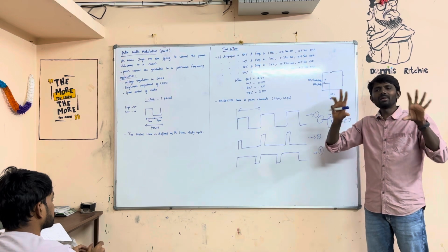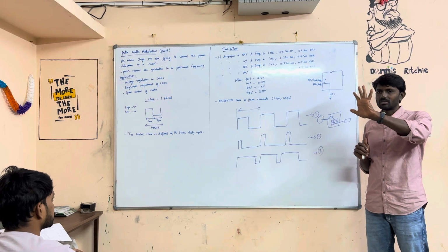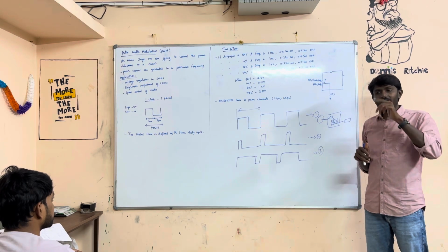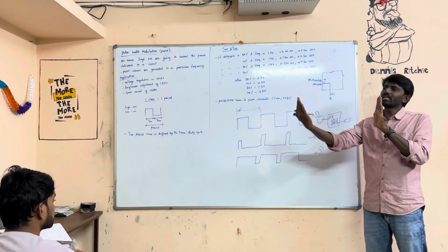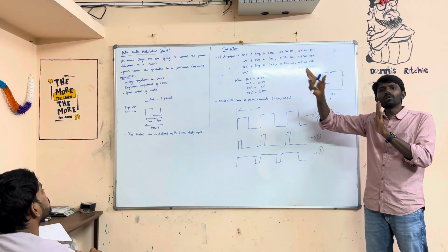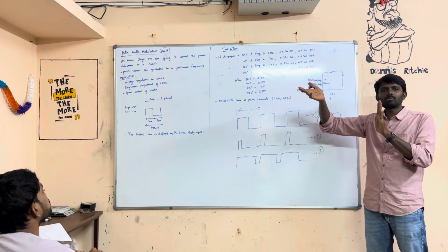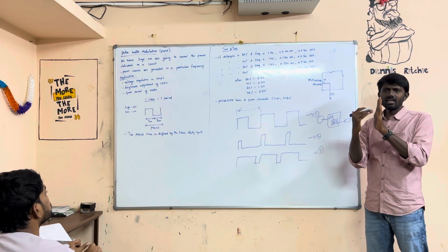That is completely digital input output port. All those 5 ports. Yesterday we have seen analog port. So in analog port only, in any of the analog channels you can give the analog input. Analog input will be 0 to 5 volt, in between any voltage, or it can be maximum voltage or minimum voltage. That is analog input.